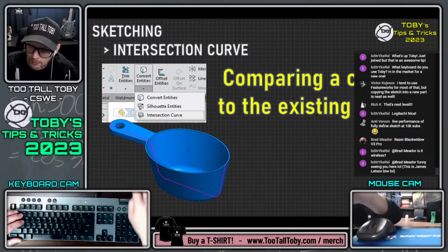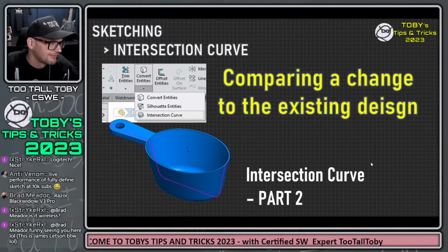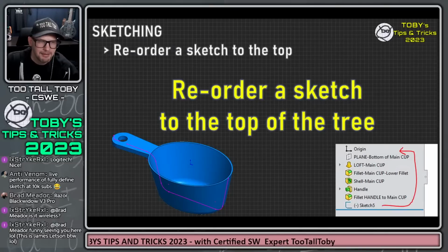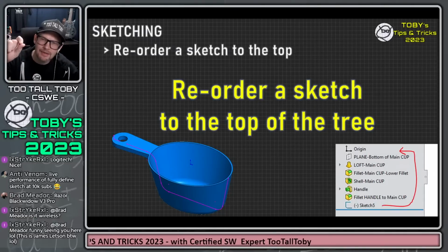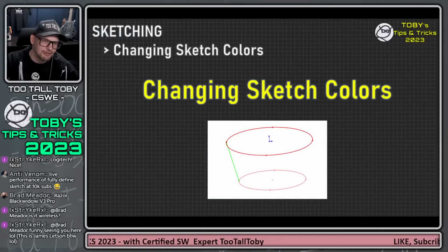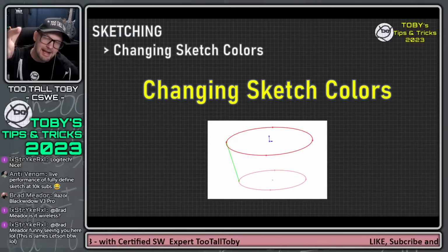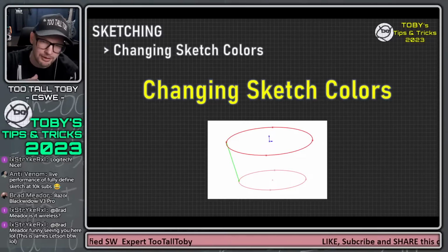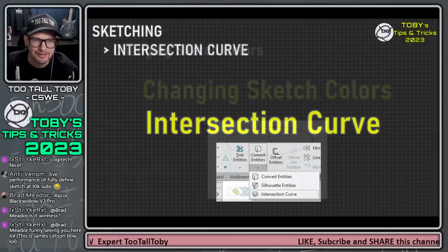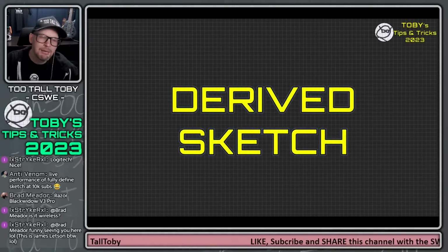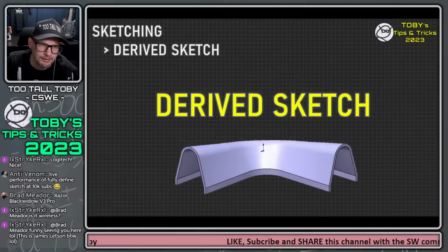Guys, I think we're winding down. Intersection curve part 2. We got some bonus tips in there. We talked about how you have to delete the sketch relationships in order to move it to the top of the tree. We talked about changing the sketch colors. This is something that I do a lot. I change the sketch colors to make sure that I can tell which one is my profile, which one is my path, which one is my guide curve. So cool stuff in there. Intersection curve. And I think we'll save derived sketch for...